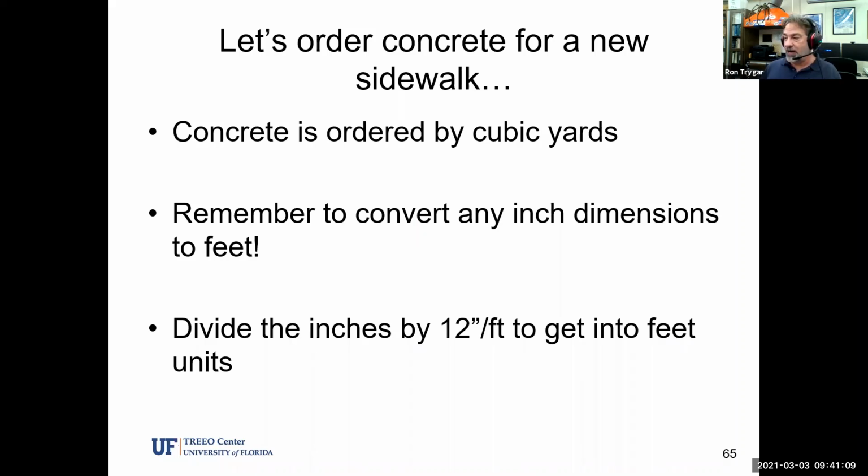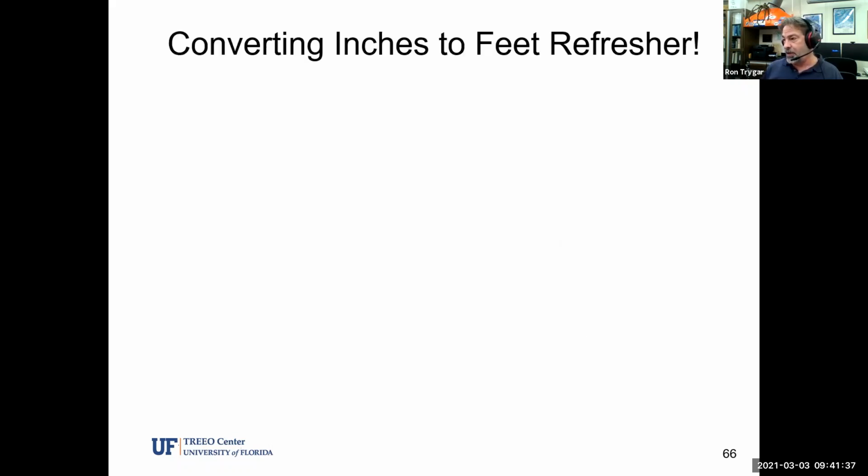So remember to convert any inch units that you are faced with into feet, so that everything is in the right units to start with. Remember, we're working towards cubic yards, and we can't have cubic inches mixed in with these feet units, because we're trying to get cubic feet into cubic yards. So we have to do the conversion first. Any inch numbers have to go into feet units first. Here's a refresher.